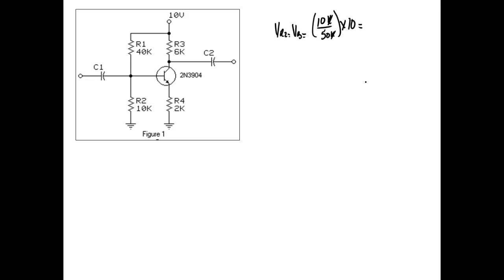What's nice about doing that is, say I get into DC and I say, okay, I've got this series circuit and it's got 10 volts applied to it, and everybody would solve it. And I say, what happens if we raise the voltage to 20 volts? And everybody would solve the whole circuit again, even though this resistor right here will always drop 1/5 of whatever voltage you have applied to this circuit.